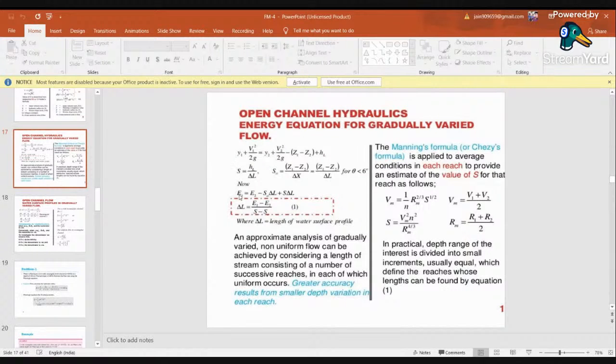When we simplify this equation, you will get a final equation, that is delta L equals E1 minus E2 divided by S0 minus SW. This is termed as the energy equation in terms of slopes over the length of the water surface. This is also termed as approximate analysis of gradually varied non-uniform flow. It is calculated by considering the length of stream consisting of a number of successive reaches, in each of which uniform flow occurs. Greater accuracy results from smaller depth variation in each step.